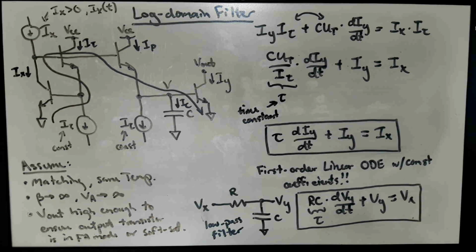That would be a typical on-chip capacitor size. Transistors are extremely cheap. You can put probably hundreds of transistors in the space that it would take to make, let's say, a 10 picofarad capacitor, if not thousands.